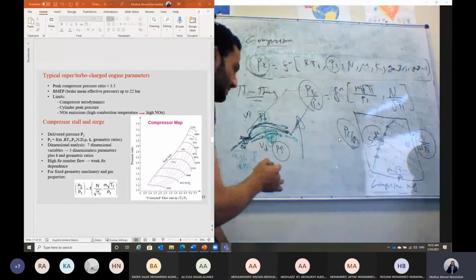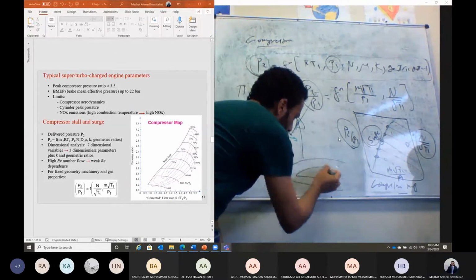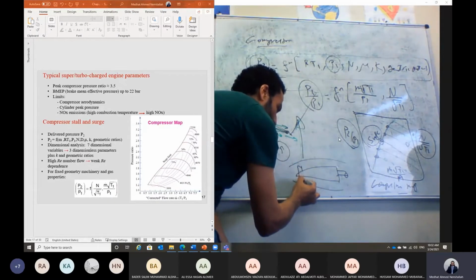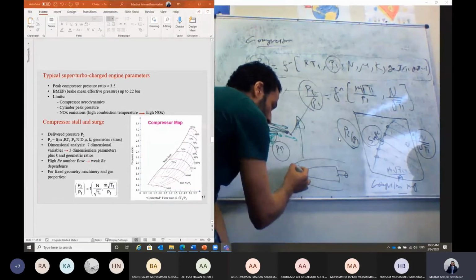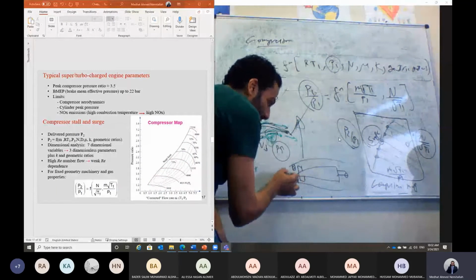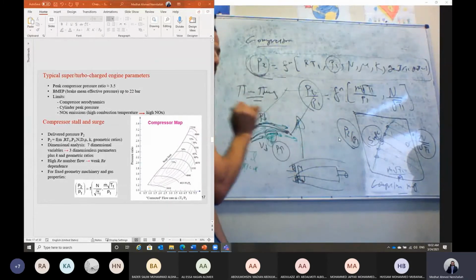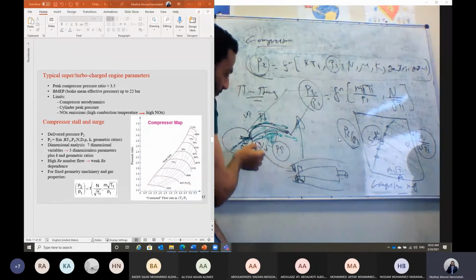If you look at the axial compressor, this is the axial compressor. This is the shaft. In the axial compressor we have moving blades attached to the impeller, and before each row of moving blades, we should have a row of fixed blades attached to the case. The function of the fixed blade here is just to direct the air to hit the moving blade at a given angle. Okay? So the air is coming to the fixed blade, which takes the shape of an aerofoil.